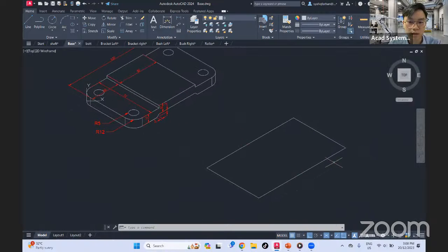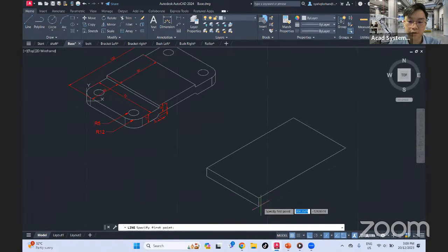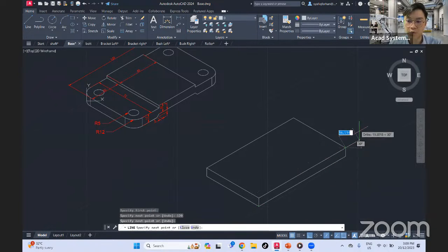And then I'll make it solid by drawing on the left plane. So moving on to the left plane, it has a thickness of 10. So draw downwards by 10. And when you go to the right side, you notice I'm actually on the right plane, and it will snap properly for me. 72, and similarly just snap. So the last part, over here, is the right plane. Just go to isoplane right and repeat the steps. 120 and snap onto the top.